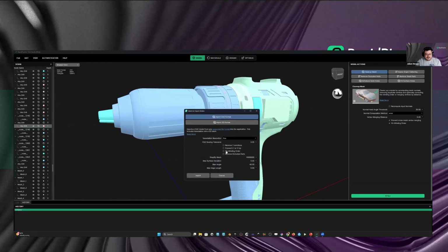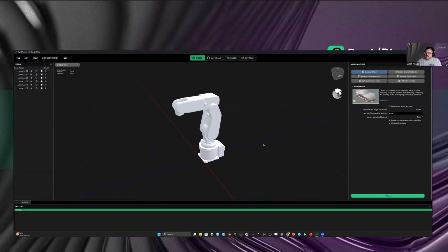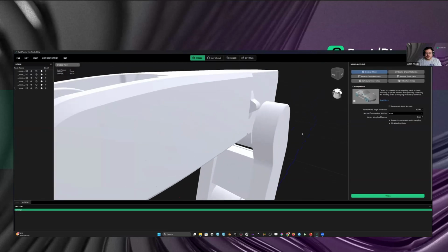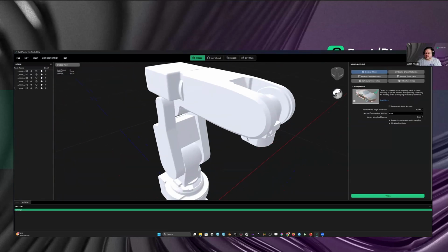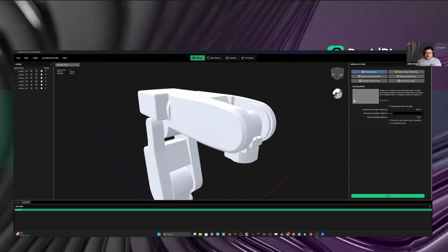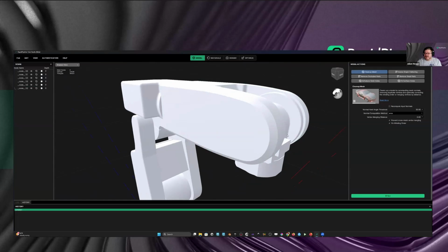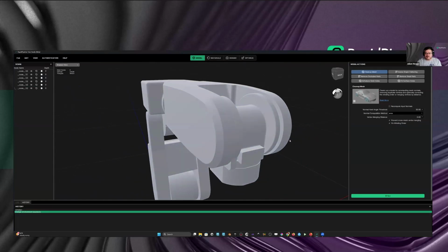Yeah, let me go with the robot and fix the winding order on import directly. And I will use it just for demonstration purposes. So I will try to break the normals, not in a computational way, but in a visual way a little bit, and then fix them again with the cleanup operation. And I'm sorry for that. I was apparently not prepared with the right example for this action. So basically what you can see here, the normals look fine. They actually look correct. Let me remove the exposure a little bit because we have the white material here.